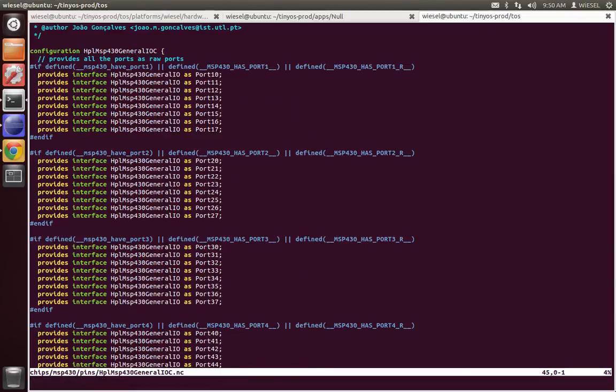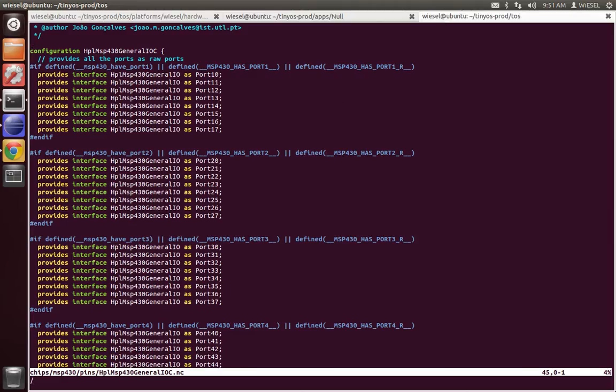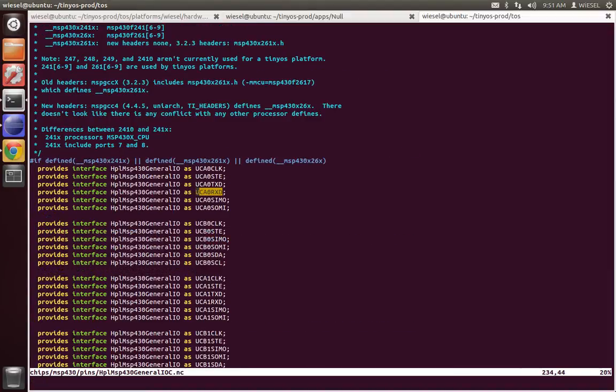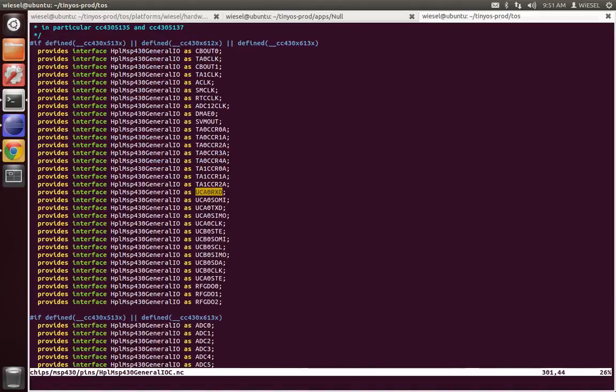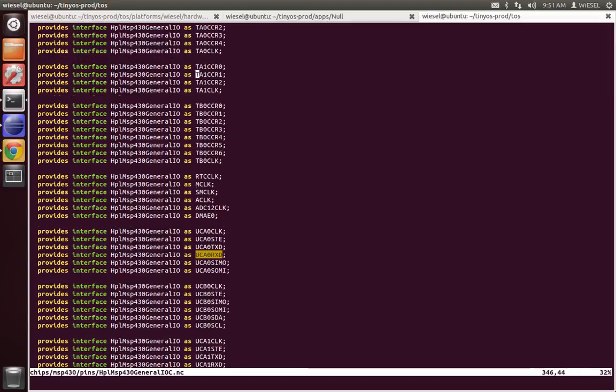directory, in here we can go and look for this guy again, the UCA0RXD. If we search for UCA0RXD, then we see that it's defined for the 241, 261, and 26X. Alright, that's good, but that's not our chip. Alright, here we go. This is for the 513, 612, and 613 chips. And there are some more in here.